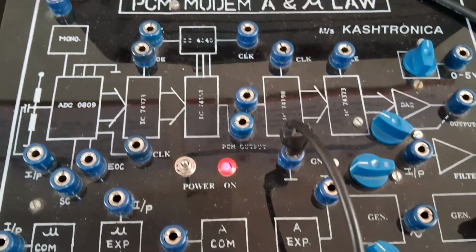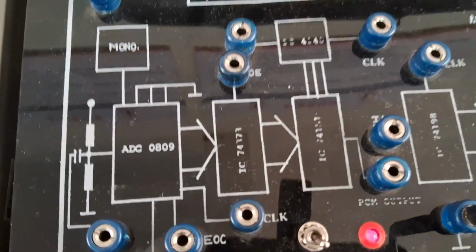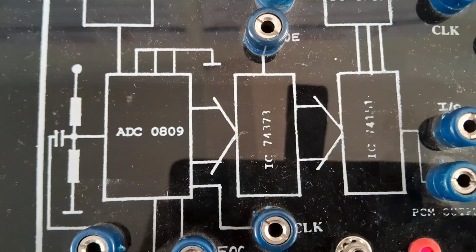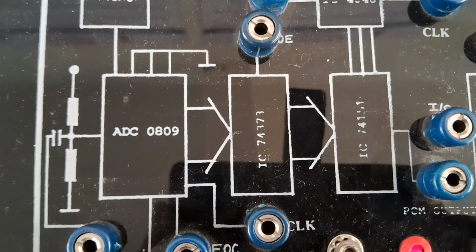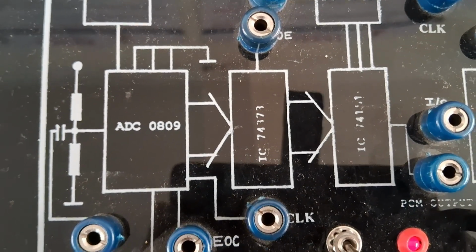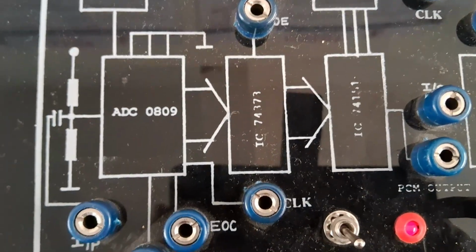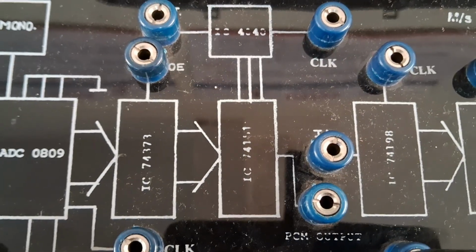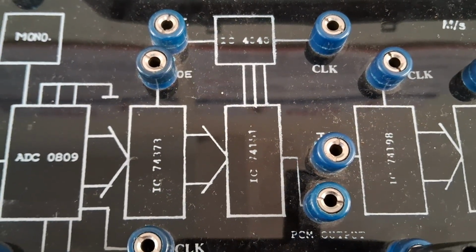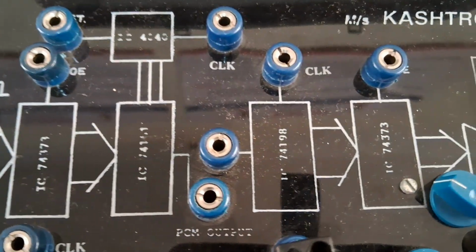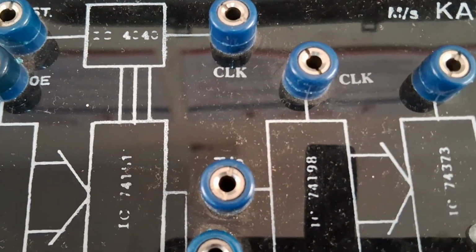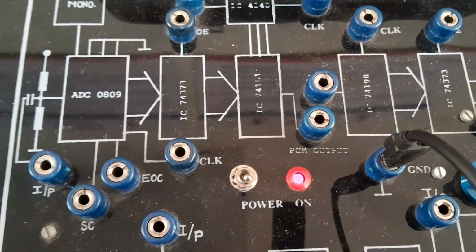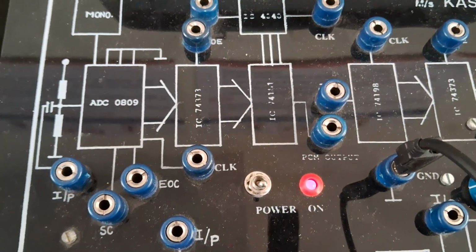So what you have is the ADC IC, that is 0809. This is the 0809 IC, which itself is a sampler, quantizer and encoder enclosed in this particular IC. After this IC, what you have is a latch, the 173 IC, and then a parallel to serial converter, that is the 151 IC, which has been used. Now what is the input to this particular ADC? It is the analog input.